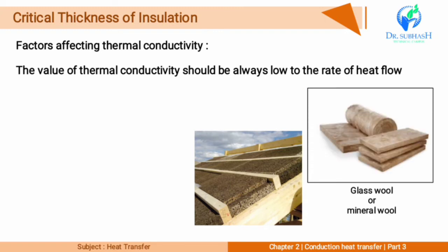Also, there are some important factors which affect the thermal conductivity of insulators. The value of thermal conductivity should always be low to reduce the rate of heat flow. So number 1, the temperature. For most insulating materials, the value of thermal conductivity increases with increase in temperature.